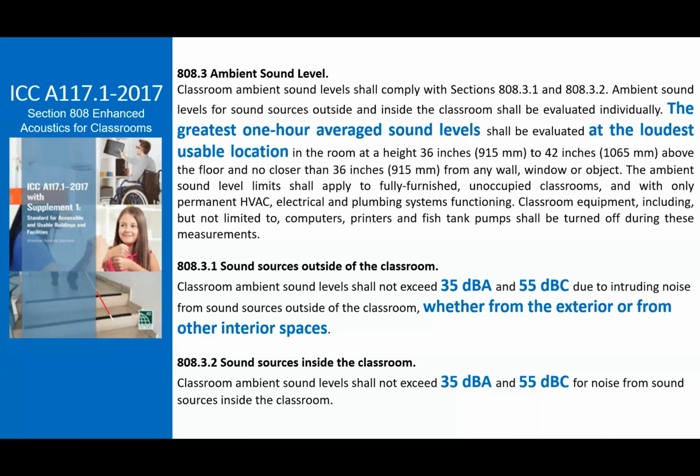This essentially means someone like an acoustic consultant would need to measure the sound levels on the site so that we can determine what the greatest 1 hour sound level is. And then it breaks it down even further into two categories: sound sources outside of the classroom, whether from the exterior or from the interior spaces.